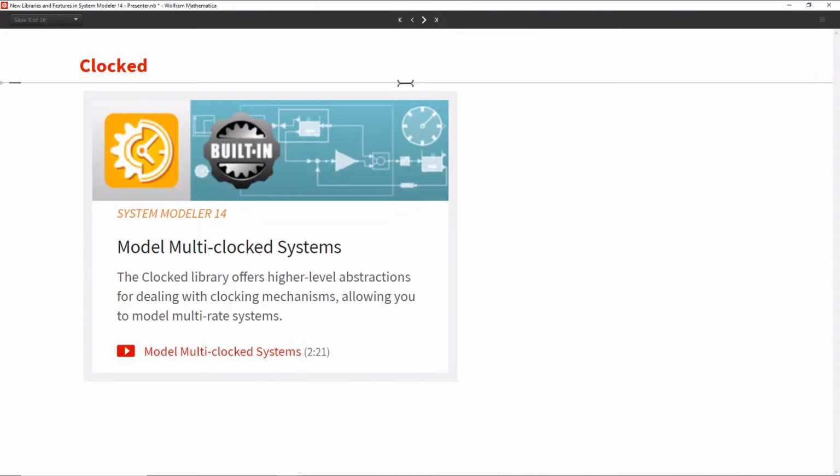A lot of real-world applications are discrete in nature, which involve periodic sampling. For example, let's say you're controlling the temperature of a room and you're using a digital temperature sensor to monitor the room temperature. A digital temperature sensor samples temperature not continuously but every 5 or 10 seconds. Measuring it continuously will require very high sampling, thereby consuming a lot of energy, and such a sensor would also be very expensive.